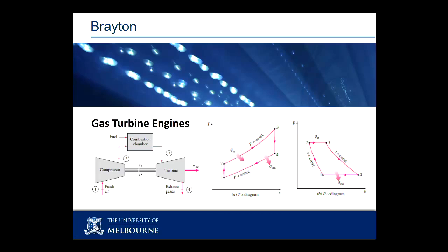There are two ways I can run a gas turbine engine. One is to produce work, like shaft work, and the other is as propulsion, as my aircraft engine. When I'm producing shaft work, the turbine is producing more output than the compressor, and so my net system work is positive out. When I'm running it as propulsion, the turbine exactly just powers the compressor. The extra energy that I've released comes out as thrust, and we'll do that in about 2 lectures' time, very briefly.